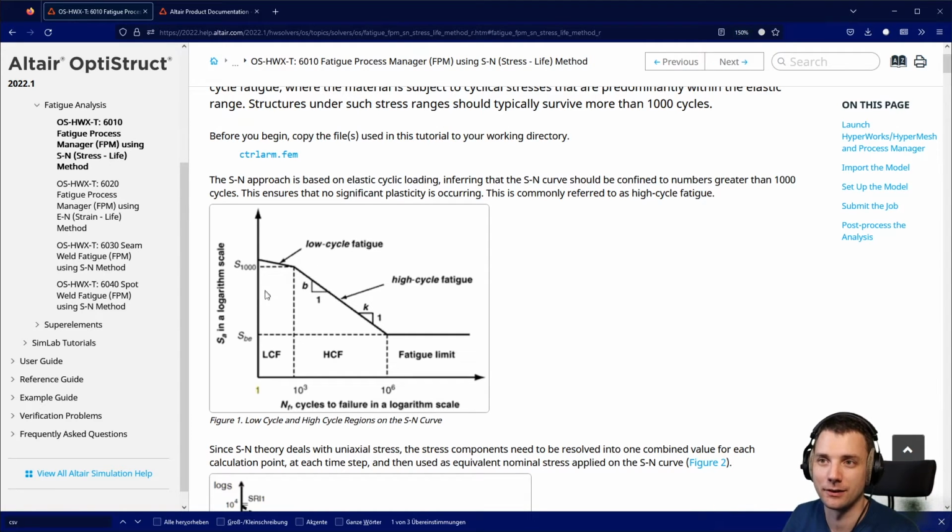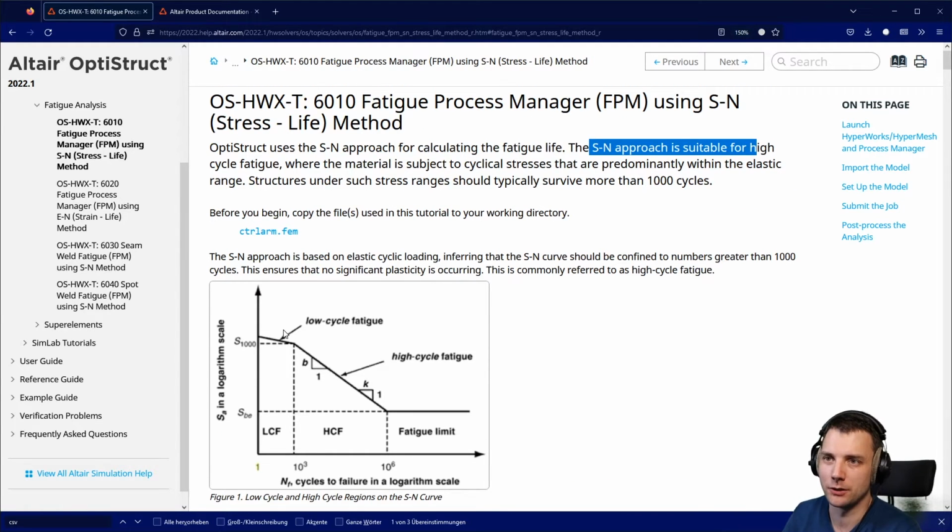And it does this on various loadings, and it does that for some amount of time. Sometimes it will break or it will not break. Then you will just abort it after 10 to the power of 6 cycles. You will say that's fatigue safe, I think it's a term. And you see that there is low cycle fatigue and high cycle fatigue. The magic boundary here is 10 to the power of 3. So below that, low cycle; bigger than that, high cycle.